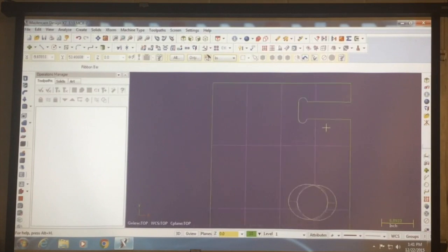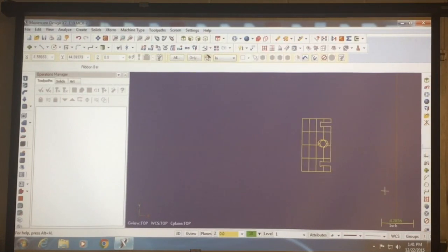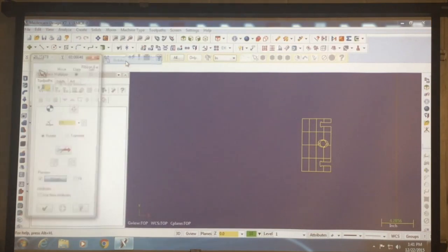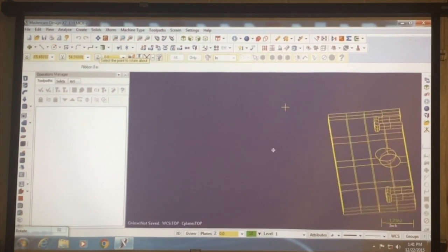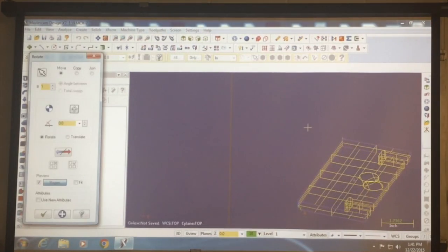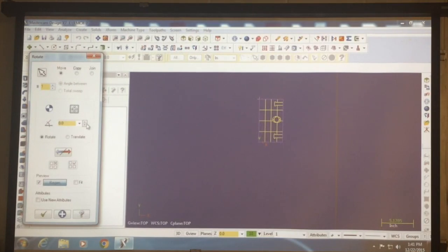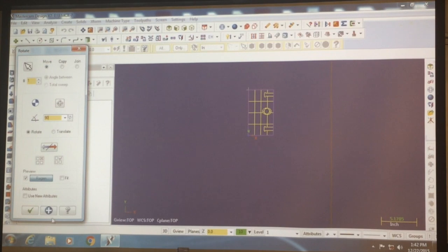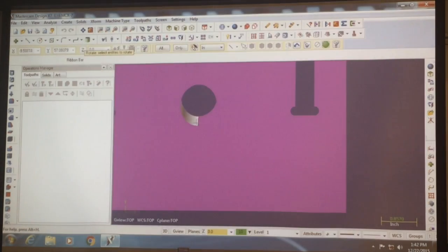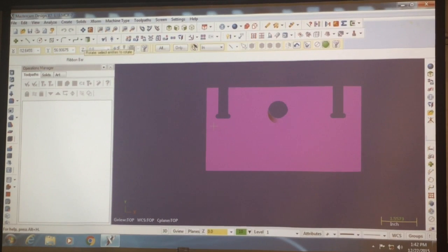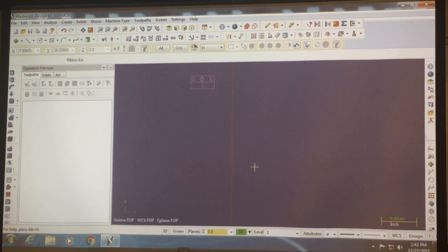So then top view again, and we're going to select it, and we're going to export and rotate and move. We're going to rotate about this point. We'll rotate 90. Alright. So now we have solid view, this bottom area being solid. Alright, so escape now, and we go back to wire view, and we want to locate it where our 0,0 plane is going to be.